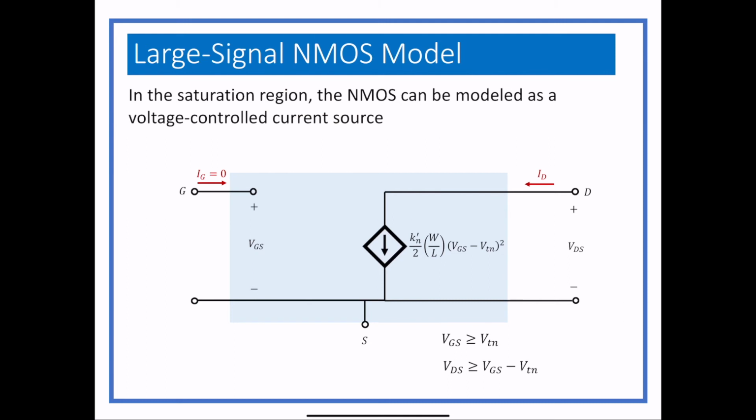And basically what you have to do is pulse the voltage. So you have to pulse values of voltage, read the current, and then lower it all and let it cool down and then do it again. So it's an automated process. If you can automate it, which people who know how to do LabVIEW can do, then you can actually get characteristic curves, but it's not easy. So this is what actually ends up happening.